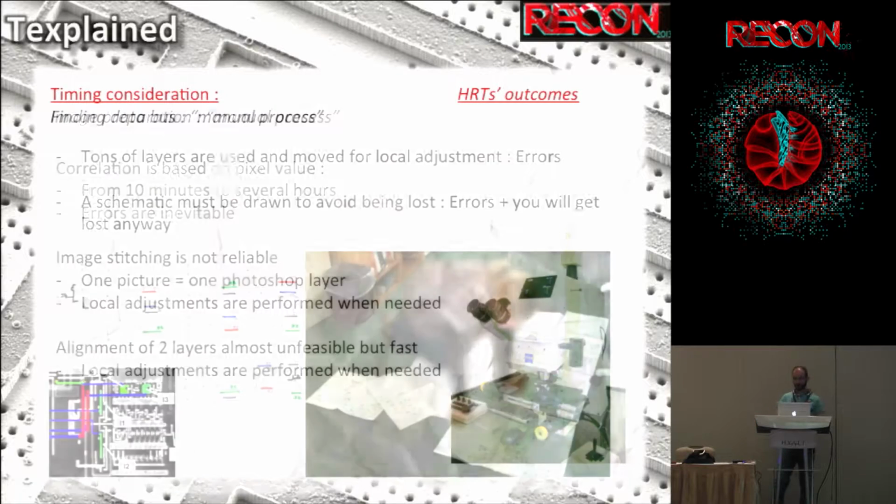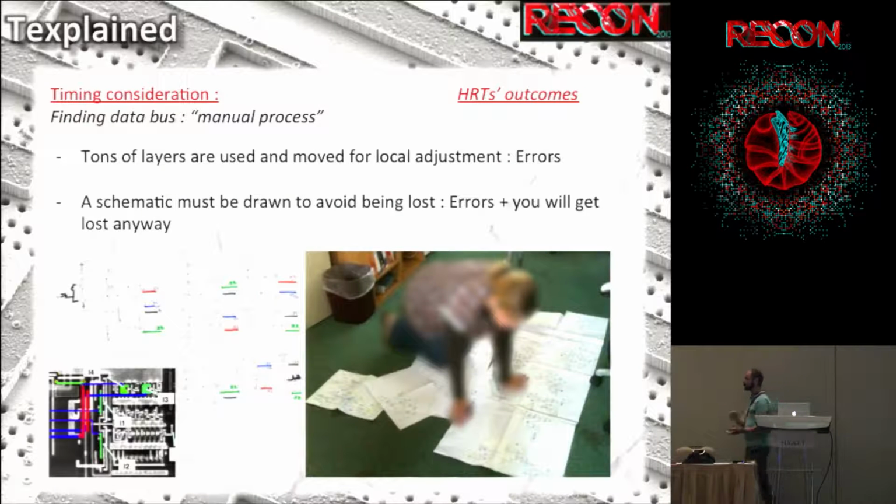And now what you do is you trace your lines by hand, I have a line here, and a line here, and here a line. You have to go from layer to layer, find the gates, identify the gates, write down what it is. And it's huge. We are speaking about huge. In that case, it's only 1,000 gates, but still, and you will start to draw a schematic somewhere, not to get lost. And if you do it with paper, you will have paper everywhere, with schematics.